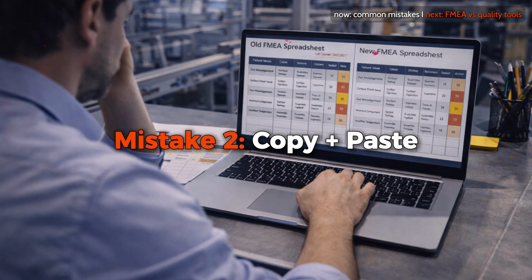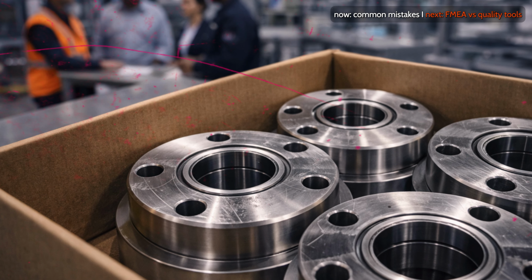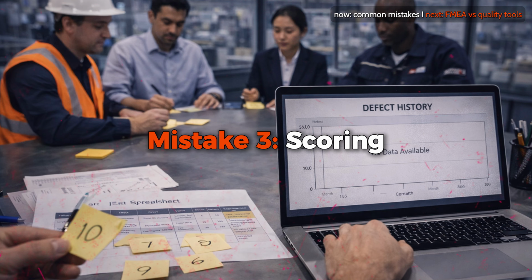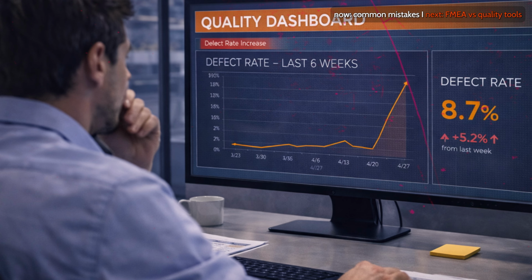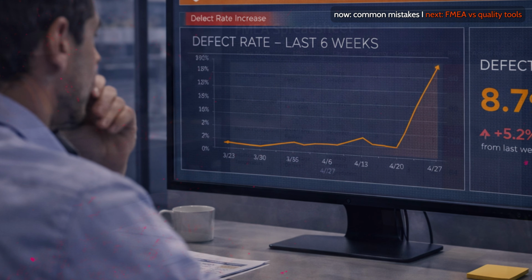Mistake 2. Copy-paste from previous projects. Another mistake is copying an old FMEA without analyzing the current situation. The packaging process for one product may not apply to another. Assumptions replace analysis, and real risks remain hidden. Mistake 3. Scoring without discussion. Teams sometimes assign severity, occurrence, and detection values without real debate or data. For example, rating occurrence as low without reviewing defect history creates false confidence. Risk scoring must be evidence-based.